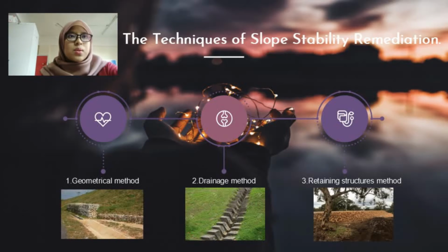Choosing an effective slope stabilization method necessitates a detailed study of the current slope condition as well as an assessment of the mechanism of slope instability. There are several ways to stabilize the slope. The embankment overhaul approach includes changes to the embankment shape, drainage channel, retaining wall structure, and internal embankment reinforcement.